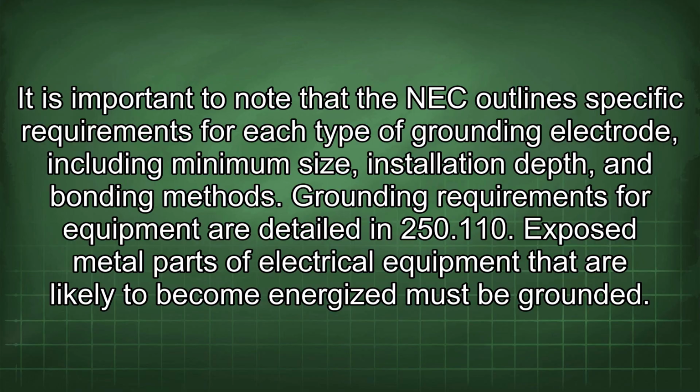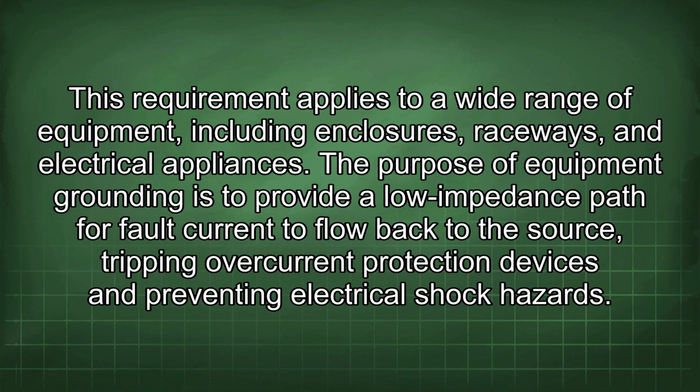Grounding requirements for equipment are detailed in 250.110. Exposed metal parts of electrical equipment that are likely to become energized must be grounded. This requirement applies to a wide range of equipment, including enclosures, raceways, and electrical appliances.